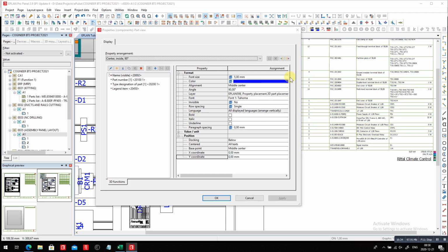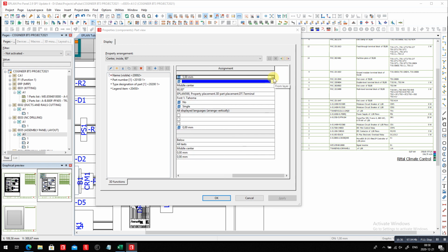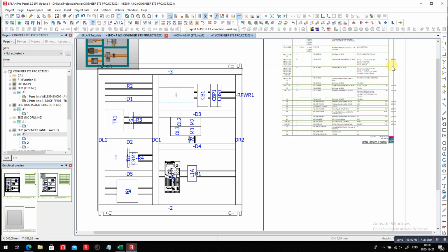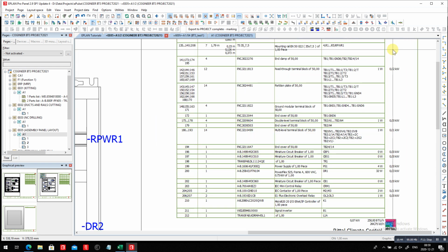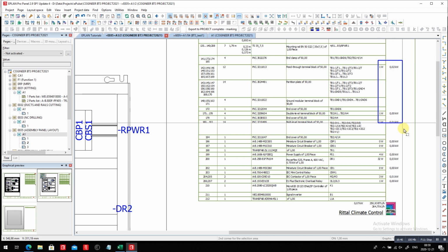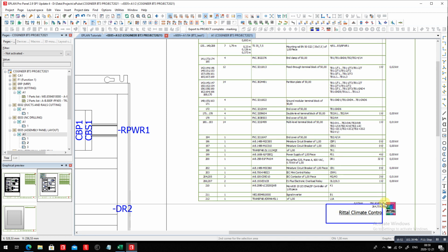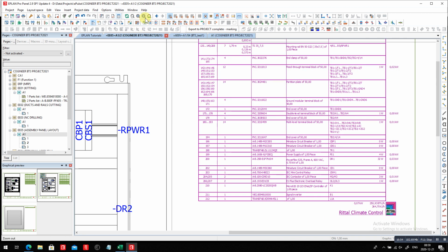And here are all the parts. This is individually every single part. We even calculate here the different power dissipation. We add them up to see if we need some climate system, either fans or climate systems that Rittal sells. So this is part of the evaluation, but also helping the guys to place the components.